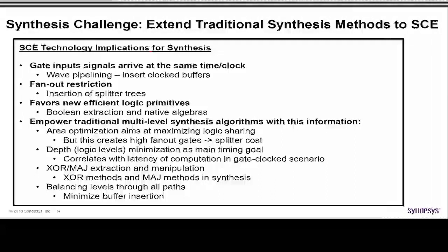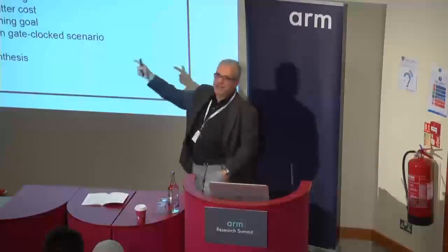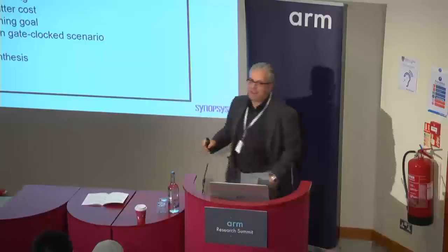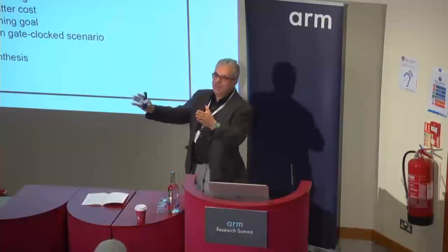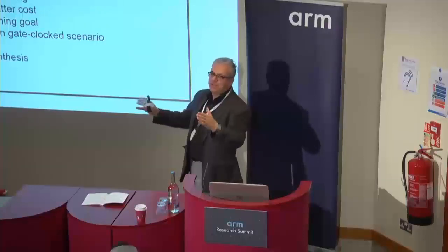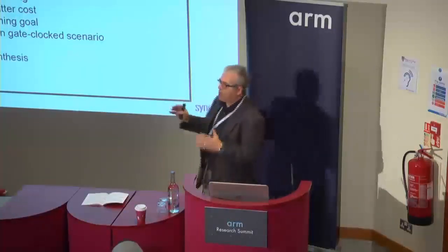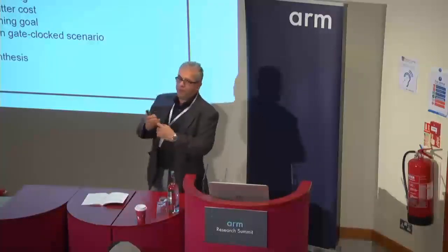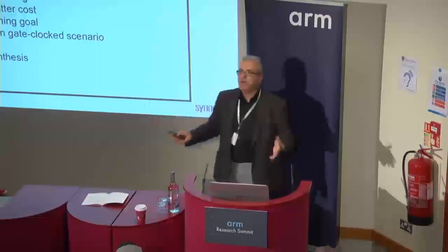And the two pulses better arrive together or have an overlap with a very, very tiny window to trigger a pulse at the output. So this is very tricky, which means path balancing is extremely important. Clocking strategy is extremely important. It's very, very unforgiving. So the question becomes, do you optimize for area? Do you optimize for depth of the pipeline? What do you optimize for?